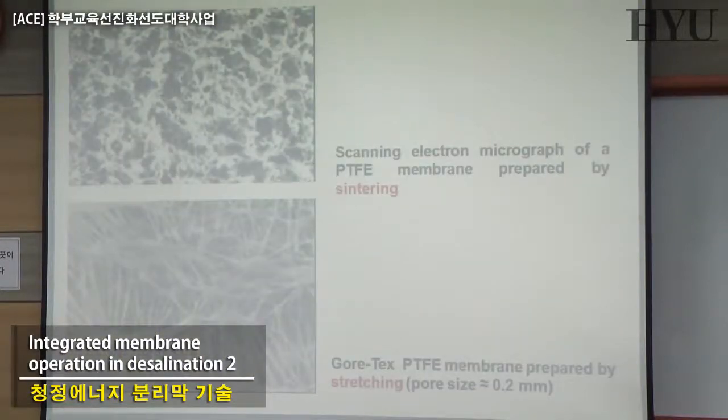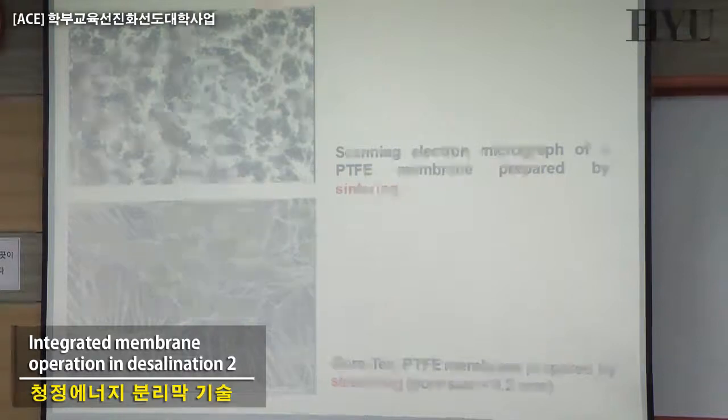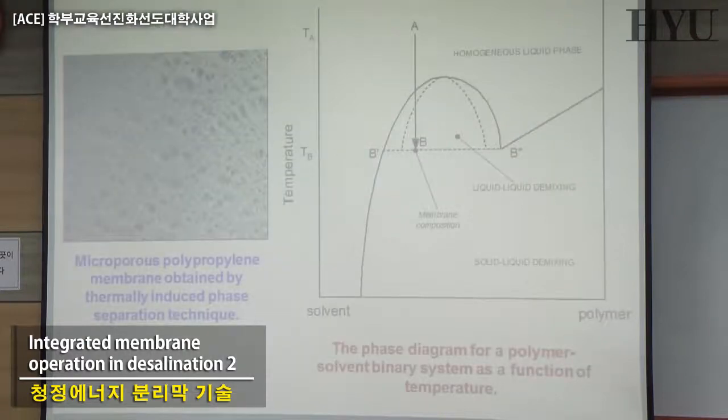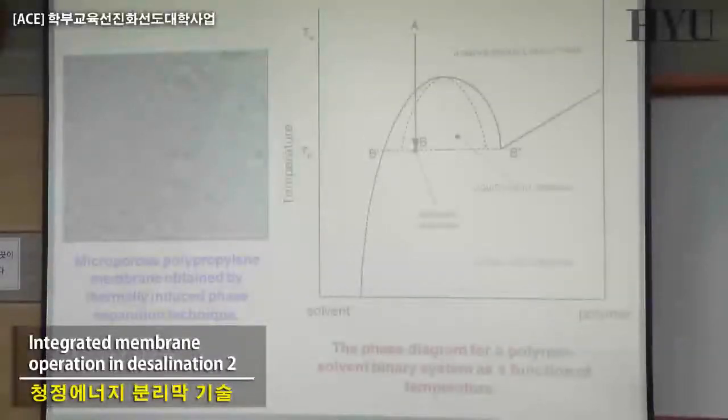And I was mentioning you can produce porosity in different ways, with the same polymer, by stretching. This one is a typical Goretex, Gore, or by phase inversion. This one is polypropylene obtained by thermal phase inversion. Accurel is the name, and that is the one, Goretex, obtained by stretching. Sometimes you can also combine the two. You can have some polymer initially produced in this way and apply stretching later on for improving the level of porosity. That is another problem, because for most of the membranes existing today, overall porosity is of the order of, they tell you, 60, 70.